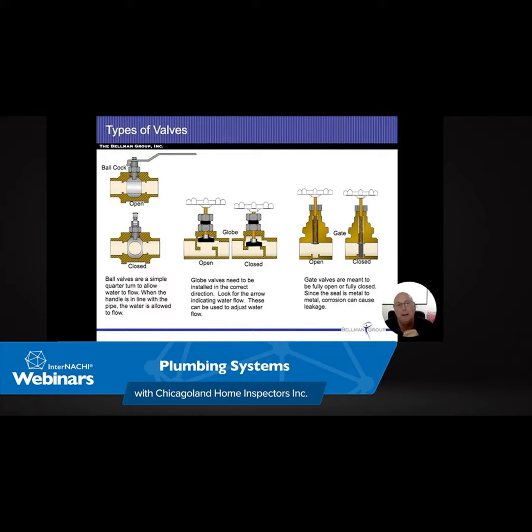This is just a cool picture. Hopefully you're going, what the hell is that? And Lord knows I did when I first saw it. This was an 1800s Victorian home in Elgin, Illinois. And there was no way in hell that the owners of this home were going to allow this thing to disappear. This is a mechanical trap on it. It's not vented. It goes straight down into the sewers. The piece that's sticking out kind of like a cone towards us, that's spring loaded. As water gets in there, it pushes that in, and then water continues to go down.